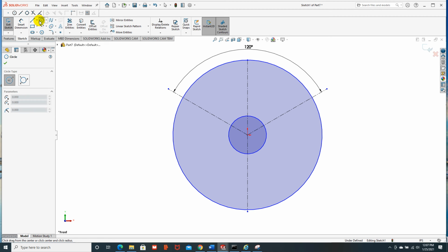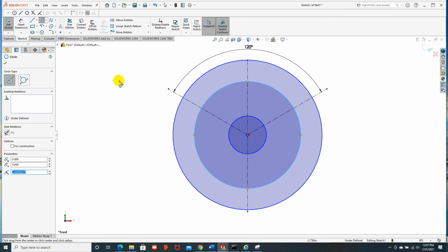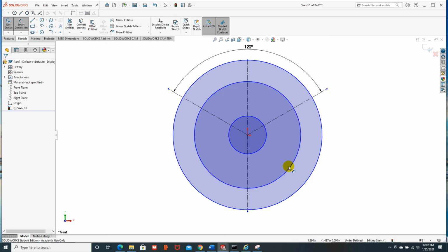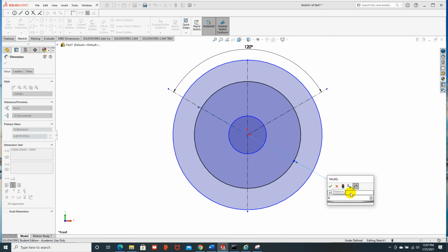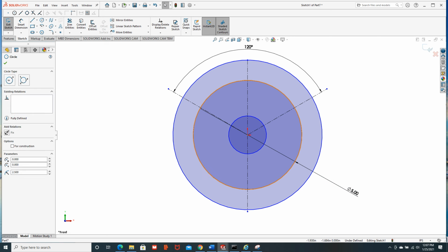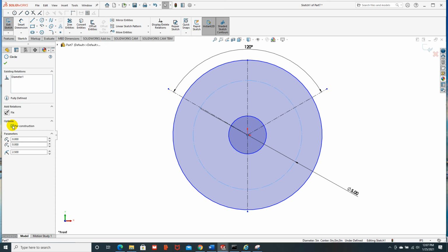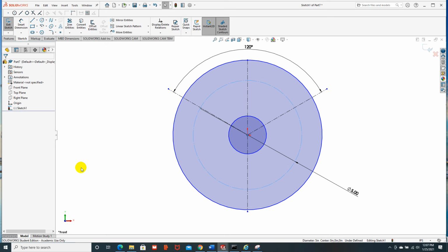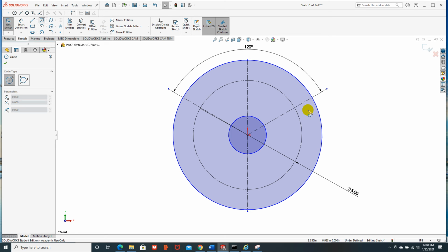And those are on a bolt radius of a diameter of 5 inches. You can also change that geometry to for construction right here. And the reason you want to set those line or circle attributes up as for construction is because SolidWorks will not try to manipulate those parts and model them.